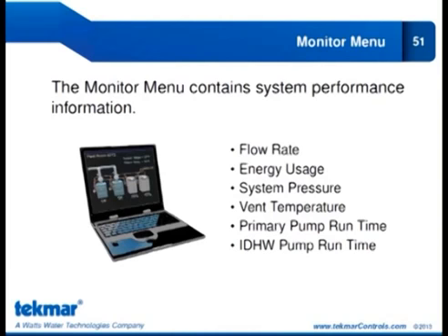And then if you have a return sensor connected, a system return sensor, now you have a supply and return, so we actually have a delta T. With delta T plus the flow rate, we can calculate the energy being consumed and display that in therms or kilojoules. Once we have that, of course, we can convey that information onto the gateway. So that's the first thing we do with the flow sensor.